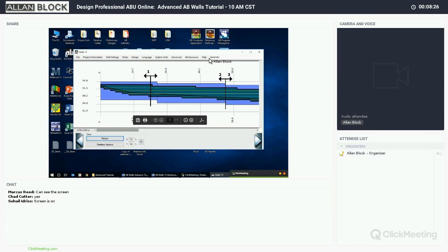This gives you the ability to do broken back slopes and surcharges and stuff like that. I'm going to minimize and bring that back up so it's a little more detailed. Then you can toggle through the different cross sections, and because we did the full wall profile, you get a nice engineer's estimate too. So you get the total block counts, all that great stuff, which is good for bid comparison, submittals, that kind of stuff. But if I go back, now we're going to get into the advanced features, and most of those center on this section screen.